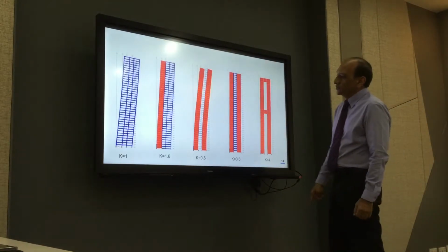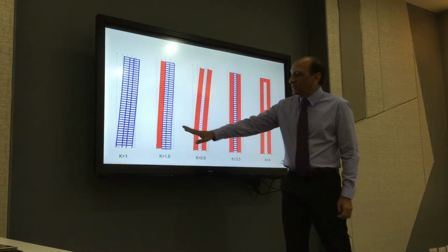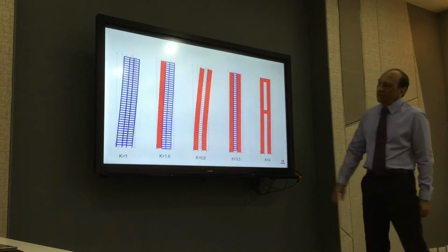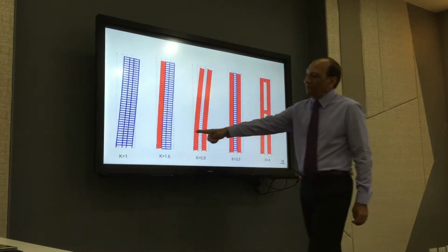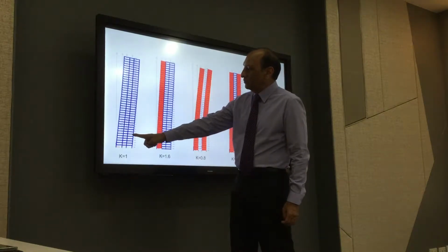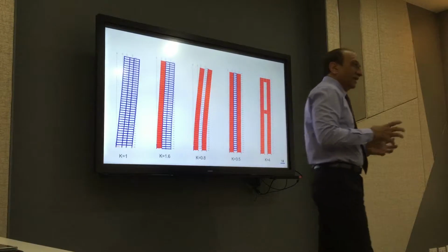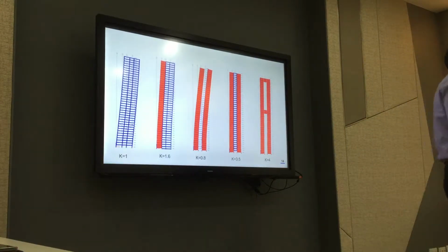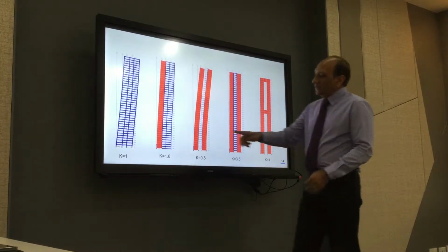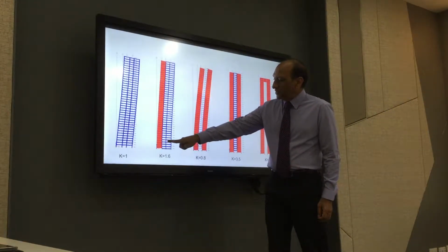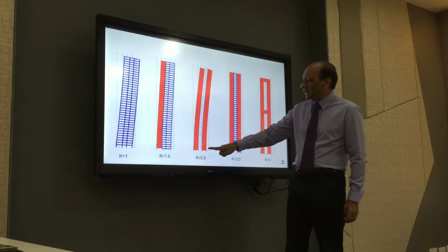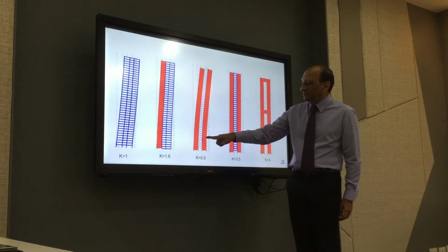And here we can compare different systems with different behavior. So if I take the frame, a simple beam column frame, which is primarily a bending mechanism because it is based on the bending of beams and columns. And then I add a wall here, but just connect it normally. And then I add 2 walls and just connect them simply.